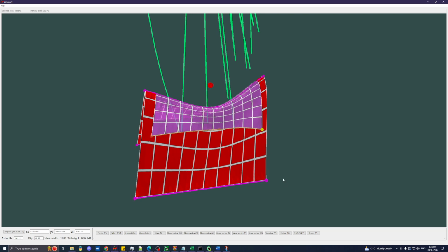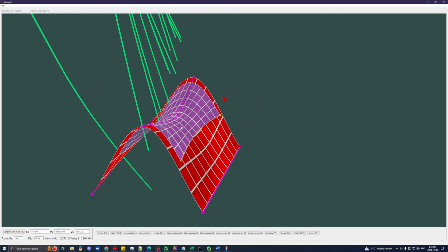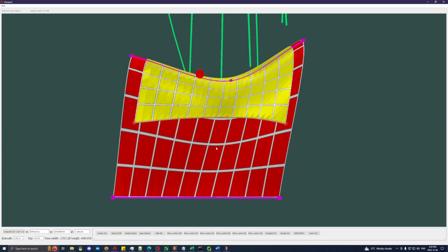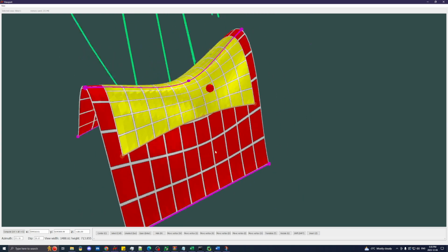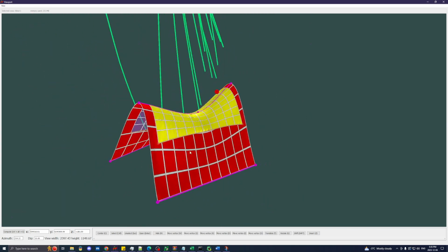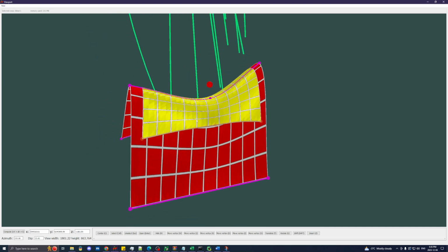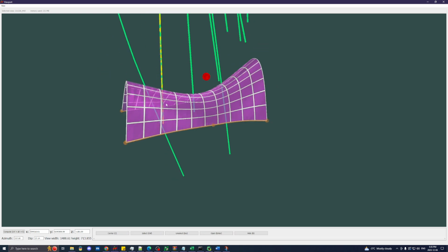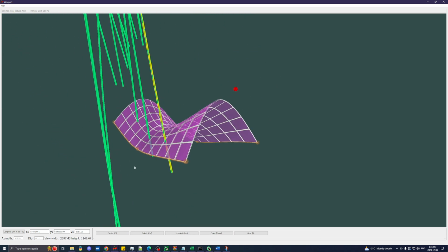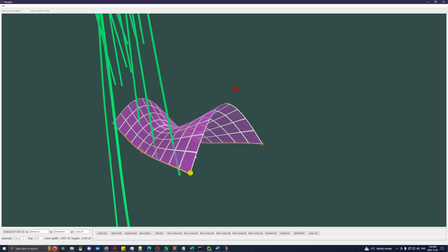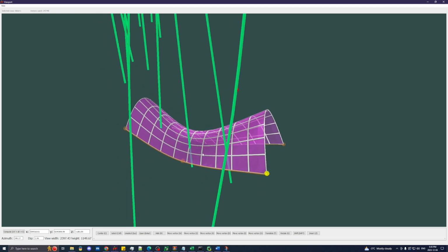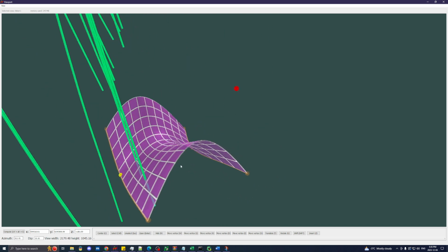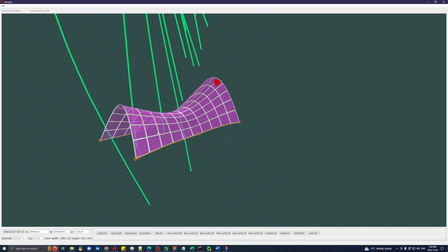And so before I go run a simulation here, a couple more things. One, oftentimes you won't have a need to have this surface visible in the viewport. So if you select the ribbon conductor and press Alt, you can see now this surface has disappeared from the viewport, but I can still drag my ribbon vertices and everything. The ribbon's still functional and you can still move it. It's just sometimes you don't need to see that canvas. So you're able to hide it using left Alt.